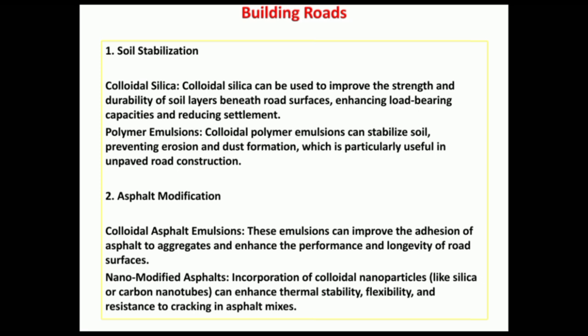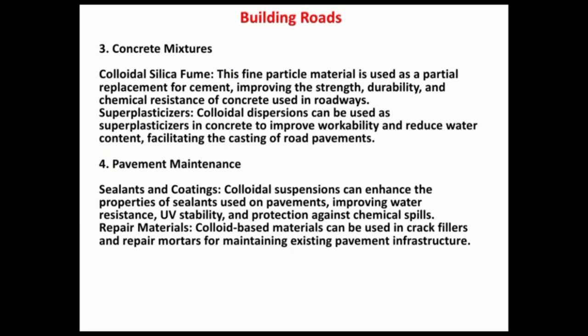Colloidal asphalt emulsions can improve the adhesion of asphalt to aggregates and enhance the performance of road surfaces. The incorporation of colloidal nanoparticles can enhance the thermal stability, flexibility, and resistance to cracking in asphalt mixtures. Colloidal dispersions can be used as superplasticizers in concrete to improve the workability and reduce the water content.